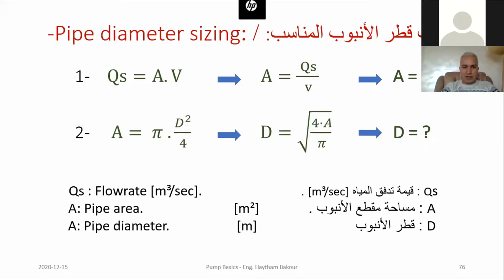By the end of this fourth section, for total dynamic head, there is an Excel format that can calculate this very simply. We need to know these equations theoretically, but everything is going to be prepared as an Excel file to calculate those. As for the flow, it equals A multiplied by V. It is in cubic meters per second.